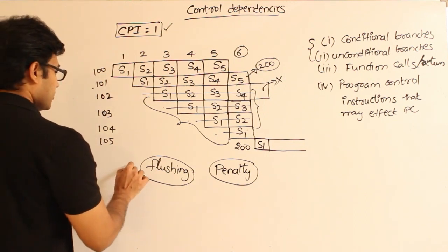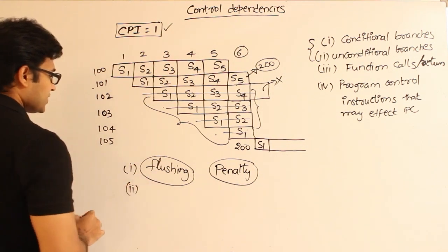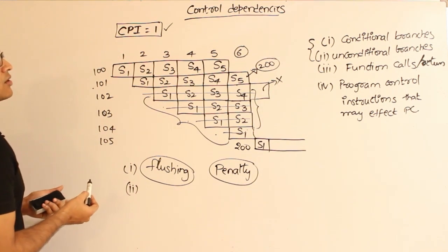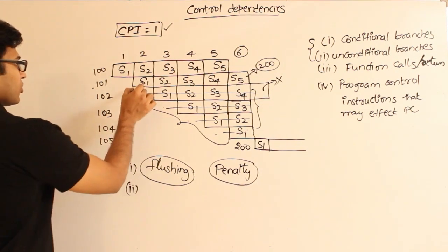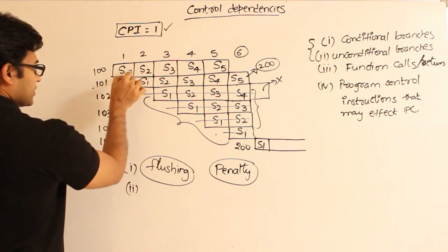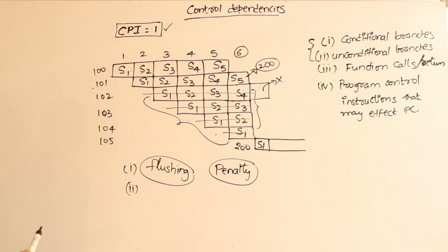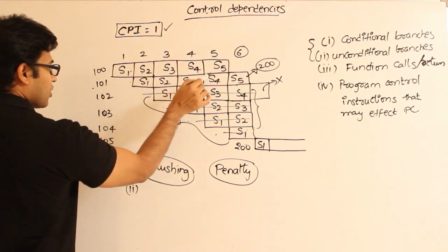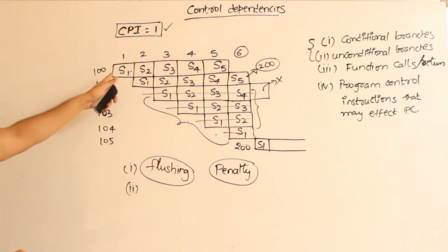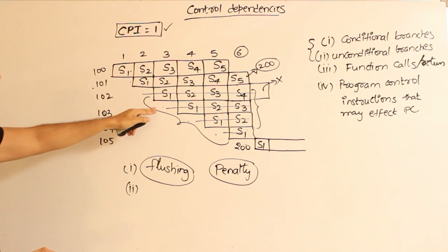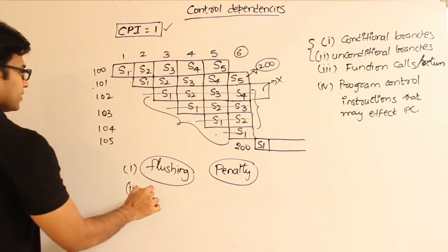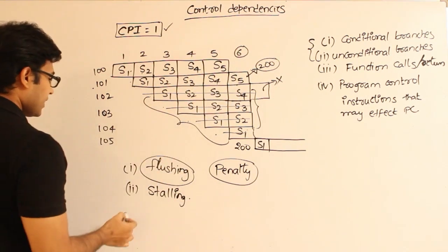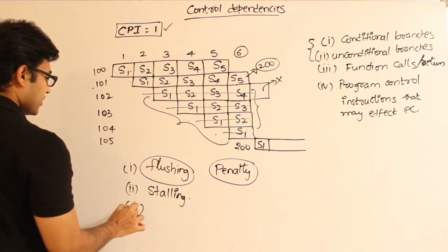And the second solution is, we have to design the processor pipeline in such a way that it should be able to detect that it is a branching instruction, probably in its S1 or S2. Let us say in S1, it has to find out that it is a branch instruction, and since we don't know which instruction to fetch after this, we have to stall, right? Stall means stop the pipeline from taking the remaining instructions into the pipeline till that one is over, right? That is called stalling the pipeline, or leaving it empty, right?